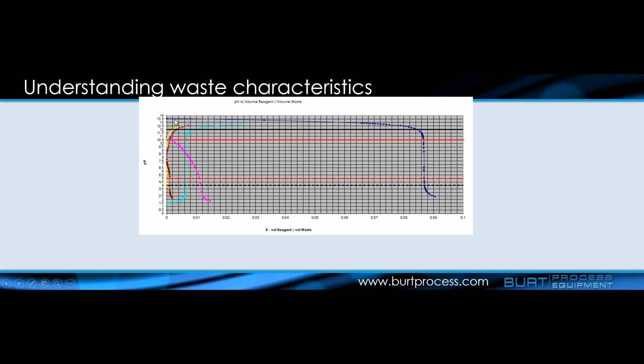The pH 13 waste stream here, you can see it takes orders of magnitude more. The tree, again, being much stronger, really highlights the logarithmic nature of pH. You're going way out here, basically an order of magnitude higher, to actually get any kind of waste treatment. So it goes all the way out and then begins to follow a bit of a linear, but even this one here probably has a bit of low alkalinity because then you get some jumping going on around the neutral point.